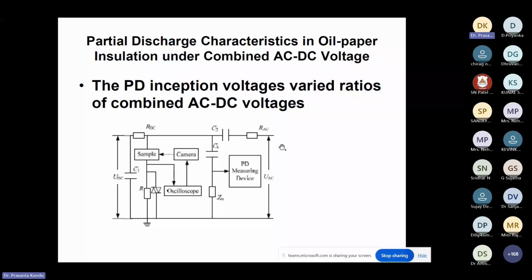On the DC side you are going to have it in both cases. So you will have a blocking capacitor so that DC does not go to the AC side. This capacitor will be the blocker for the DC, but it will pass the current for the AC. It will have that omega C, but it will block for the DC case. Omega is 0, so it is going to offer infinity. So that is the AC-DC combination in this case.